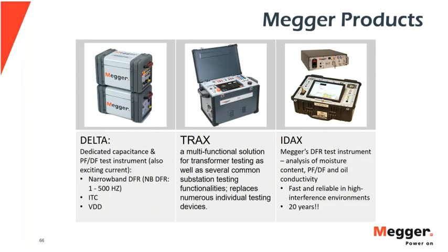And then lastly, to the far right, we have the IDAX, and this is Megger's full DFR test instrument. It will provide you analysis of the moisture content, the power factor, and the oil conductivity. And notably, it has some unique features that make it both extremely fast and at the same time highly reliable and repeatable in high interference environments.